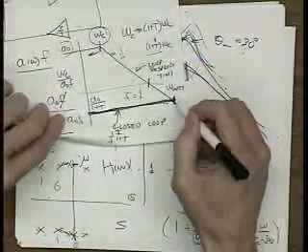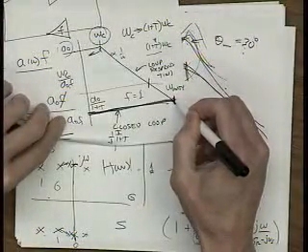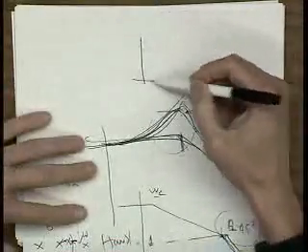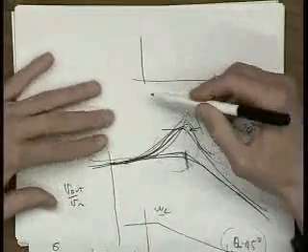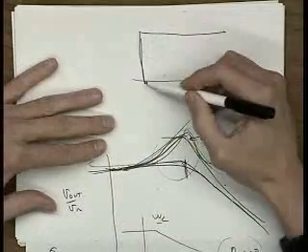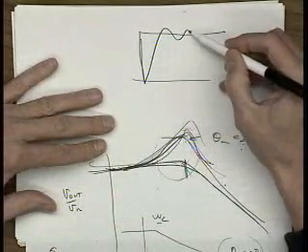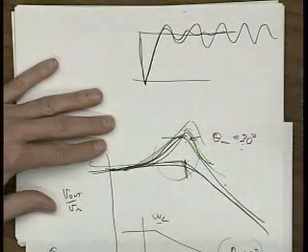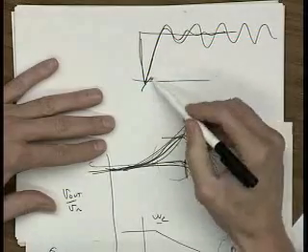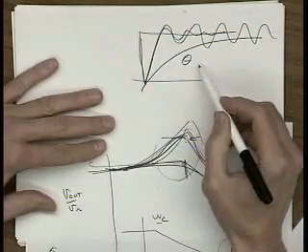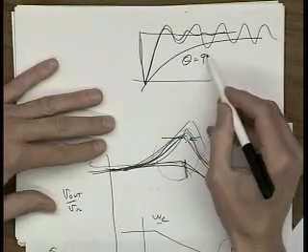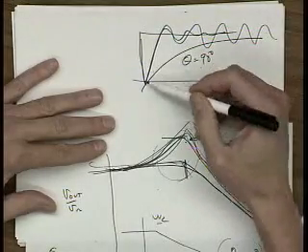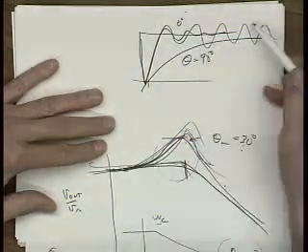I told you this related to the settling time, the small signal settling time. Well, this phase margin relates to the small signal settling as well. As you have smaller phase margin, instead of going up and staying flat, it wiggles more. It's more unstable. As it gets near instability, this thing just keeps wiggling on and on and on. As you have more phase margin, this thing gets less. So this is phase margin of 90 degrees. Okay, 90 degrees phase margin. Boy, there's no ringing at all. Right? As you have smaller and smaller phase margin, at 0 degrees phase margin, it oscillates forever.